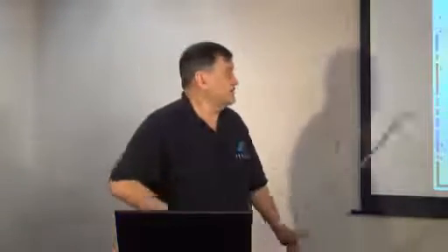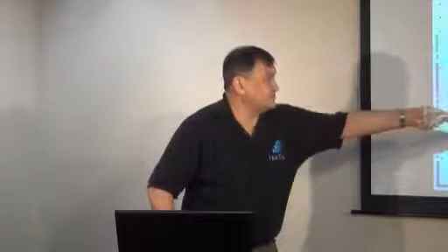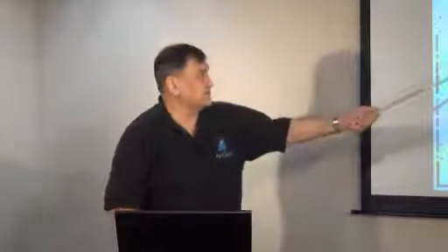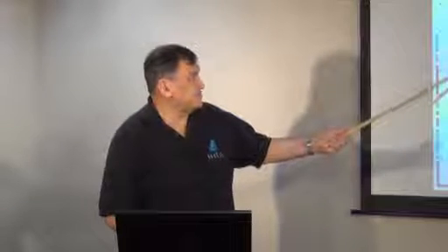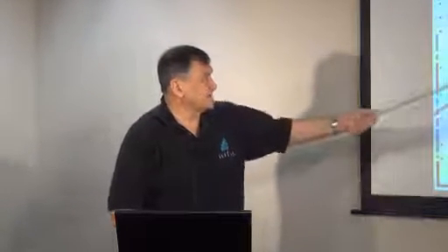They were bringing that data in so they can monitor their system. So then let's pass a certain amount of that data on up to the reliability coordinator. That working group specified that each one of these transmission operators should have what was called an ICCP node. The data would be moved across a network called NERCnet. This group started around 1998 and continues to be in existence to keep that network running.